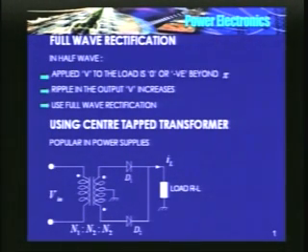When the diode is on, the load voltage is the same as the source voltage. It is independent of the type of load. You can have an RL or RLE load, whatever may be the type of load, the load voltage is the same as the source voltage.